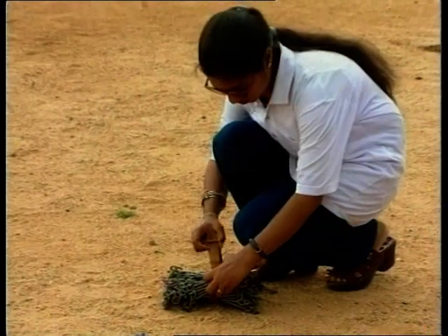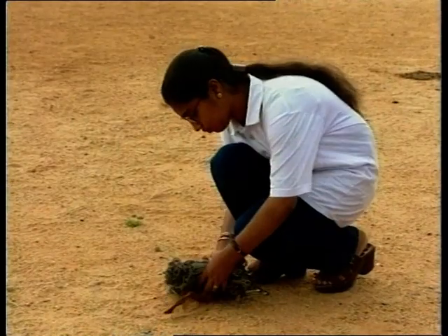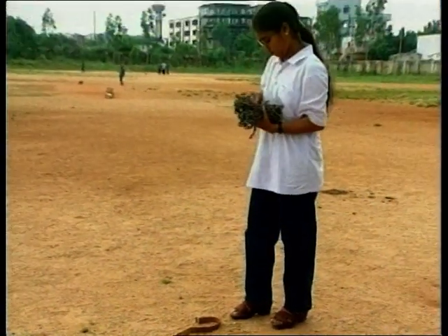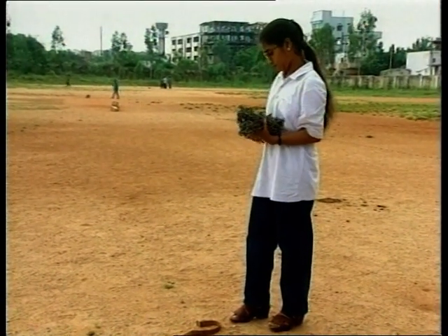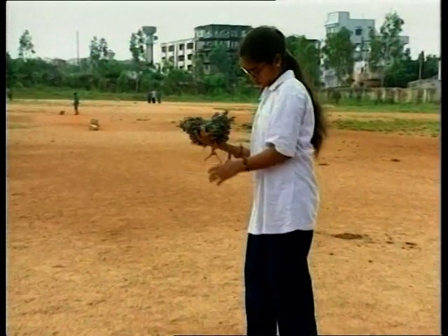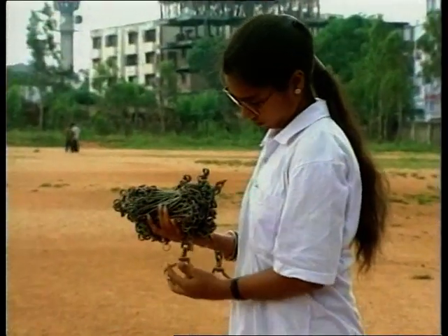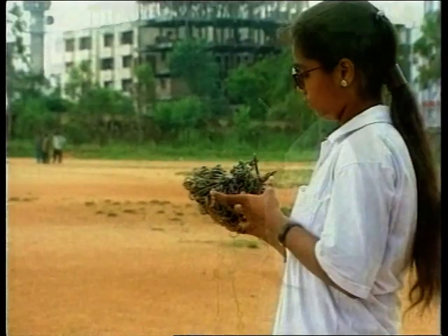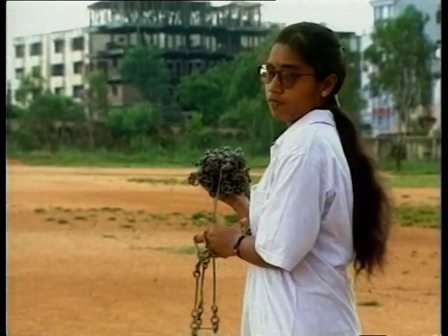Hello students, today in this class we are going to learn the technique of unfolding and folding of the chain. First let us see how to unfold the chain. First we have to remove the leather strap provided around the chain. In the next step we take both the handles of the chain in the left hand, and then taking the remaining portion of the chain in the right hand, we throw the chain in the forward direction.